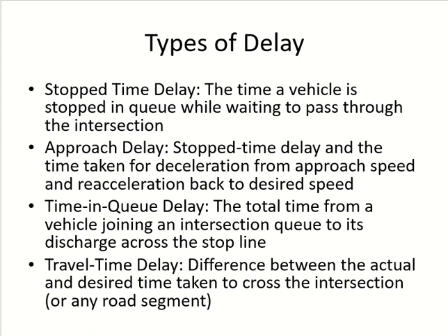Coming back to the question, how do we get the desired travel time? One approach is you take the actual one, then subtract the queue delay. You may get the desired travel time, but not always. We said use the speed limit. How do we get it? Design speed. Which speed do we call the design speed? Free flow speed. So the desired travel time comes from free flow speed.